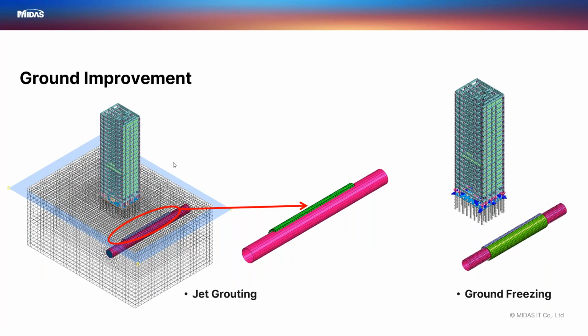So for ground improvement, there are a lot of other ways, or you can also say that, let's say if you have a very thick shield, you can use that too for controlling the pace of tunneling. Otherwise, in some cases, you definitely need some ground improvements. So in this case, you can see what we have done is we applied jet grouting to the left edge of the tunnel as the tunneling moves adjacent to the building.